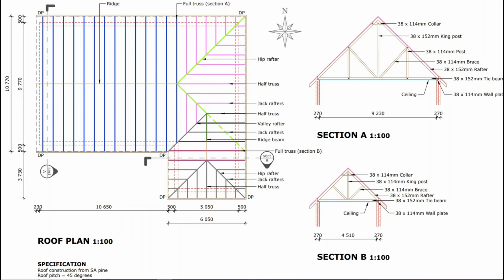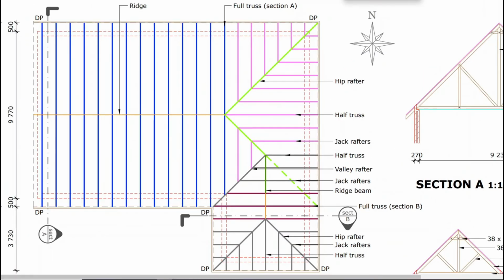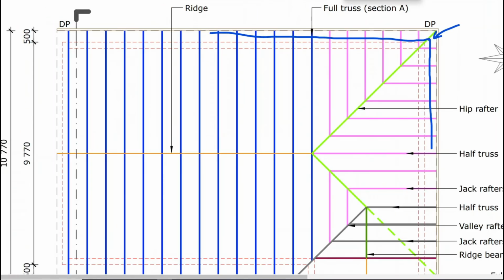So all we're saying is that you can apply cos to run up the slope, but there are instances where you need to reverse apply it. And that one instance that I've seen is where you need this first batten's length. And you don't need the other ones, but I'm sure it could be asked eventually. But this first batten, that length that is short is not actually its center to center dimension. So if we're saying a center to center is 345, that is center to center on slope.